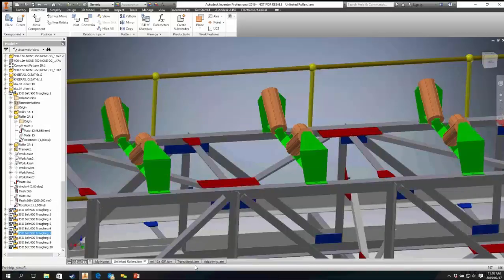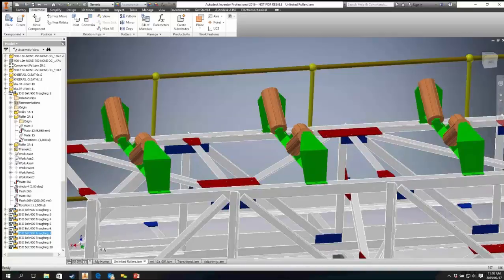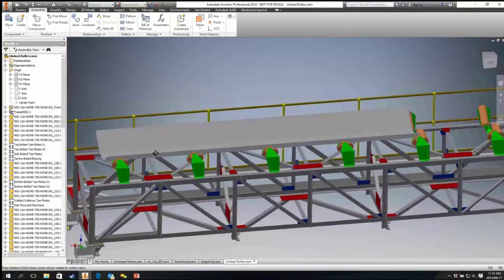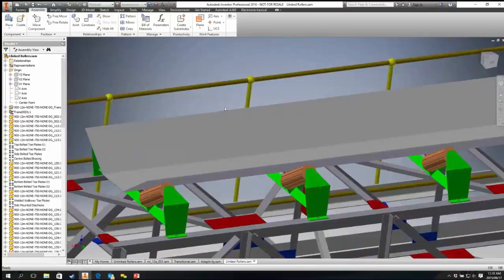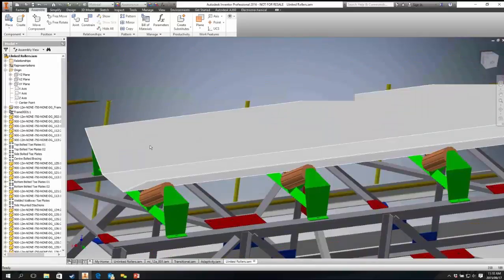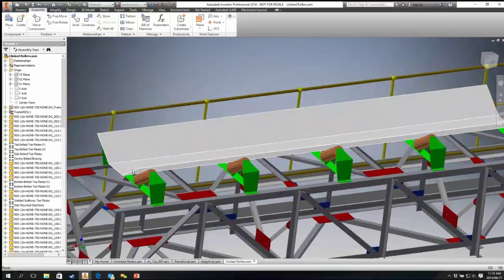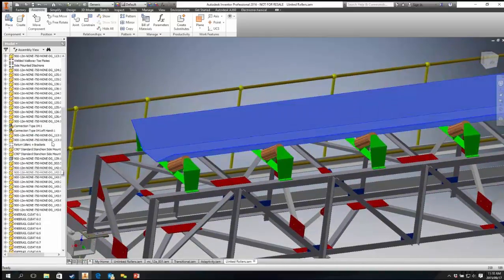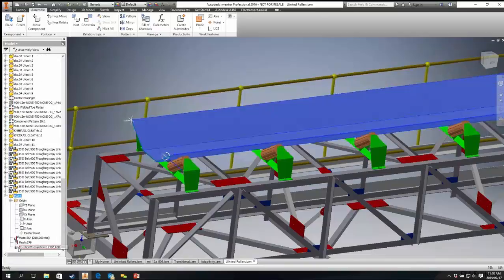if I have the actual conveyor system itself, and bear in mind that I didn't make this adaptive to change in size or direction, but if I did, when I go and use this, and you'll see, just to give you an example of what I've done, over here I've used that rotation translation on this face to say, as this face moves linearly, rotate the wheels using this rotation translation.